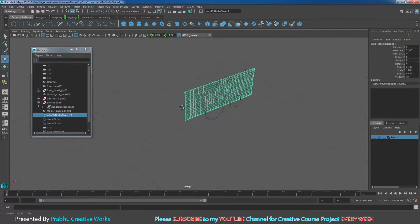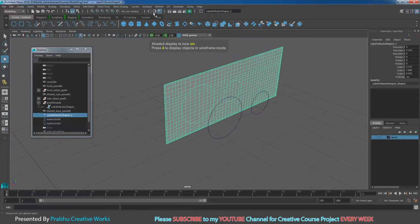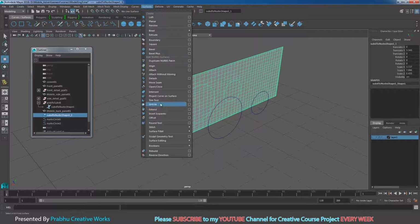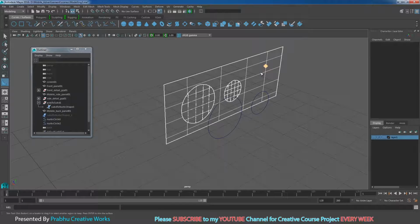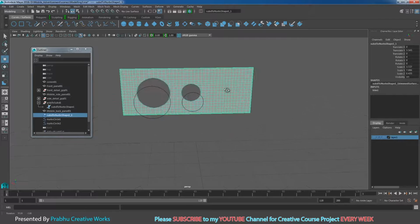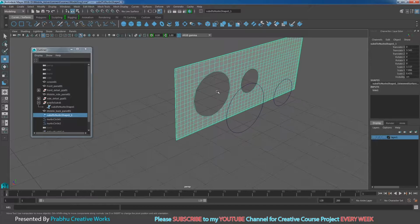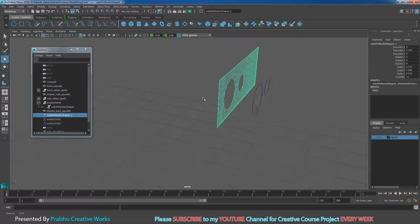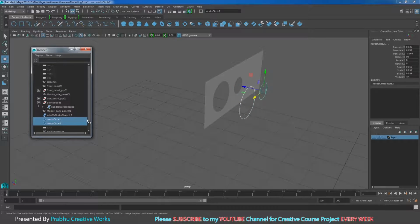Now I select my knob shape over here. Press 5 on the keyboard to see the shaded mode, go to surfaces and choose trim tool. Click anywhere on the outside, don't select the inside, and press enter on the keyboard, so it will be perfect. Now I want to make a duplicate curve over here, so I will clear this history. Select this knob shape, go to edit, delete by type and choose history. Then select both knob circles and press delete.